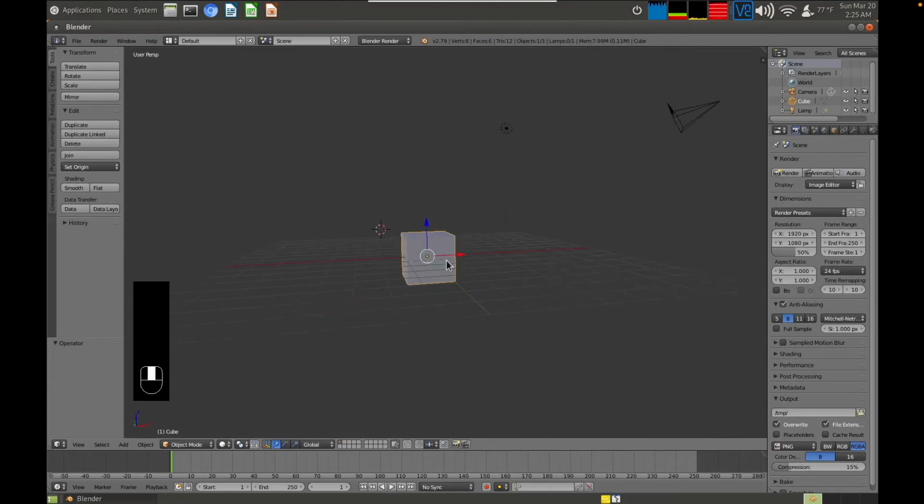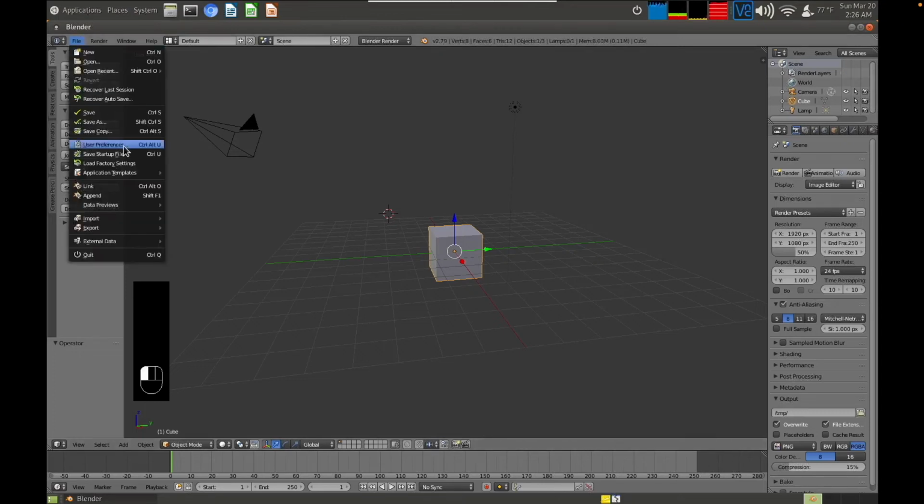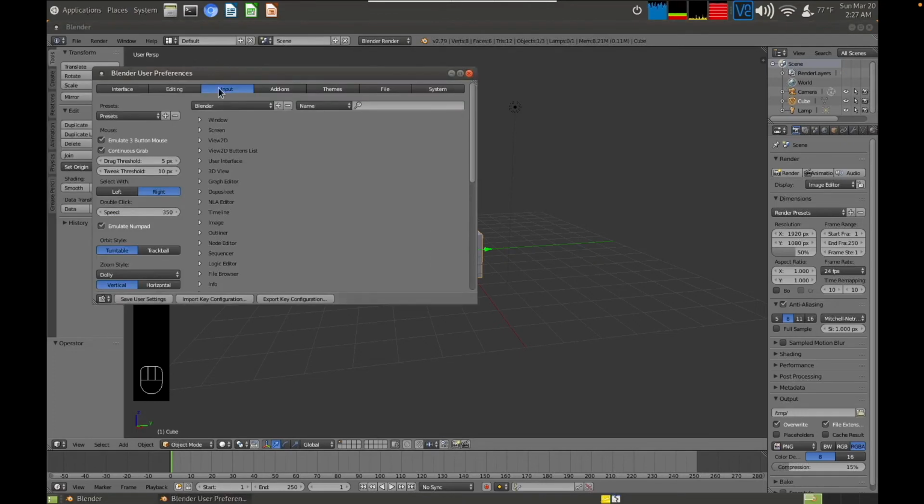So with those three actions, you can move and orientate around the scene here, or the objects that are here, okay? Right now we only have the three objects. And like I said, you don't really need to worry about these other objects right now. The other way that you can navigate very quickly is by using the number pad. Now, you guys have smaller keyboards, so you don't have number pads. So what you actually need to do is go up here into File and then go to Preferences, User Preferences, and then click Input, and then click Emulate Number Pad.